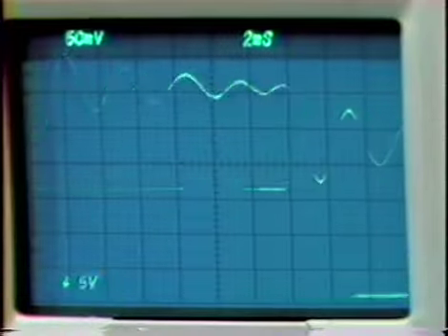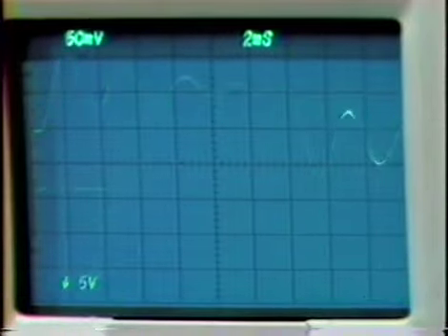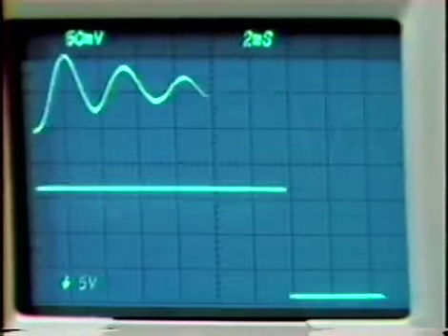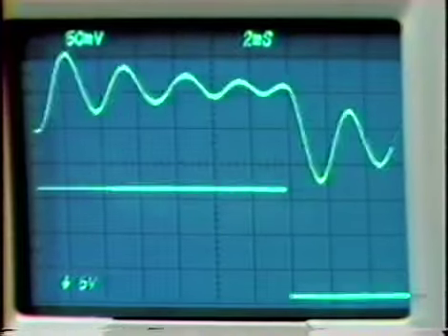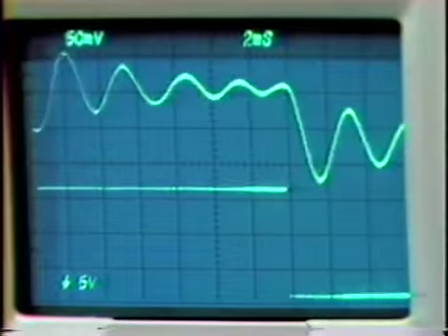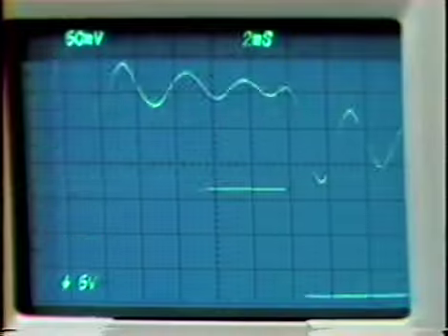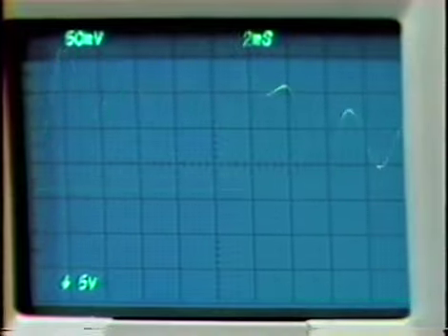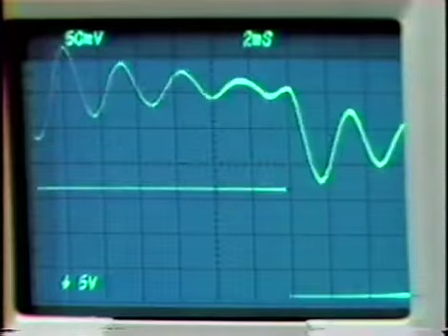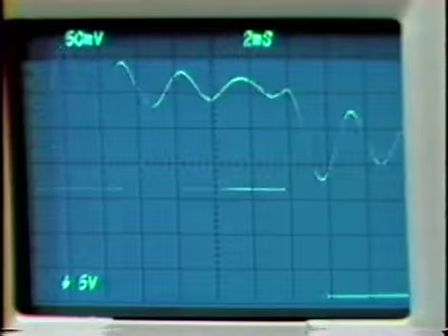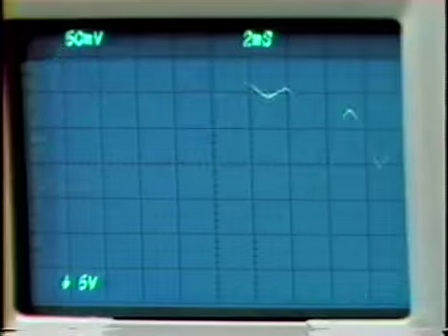We notice on the signal relatively small, we don't really see much ripple at all from the phase detector. This particular system is working at a carrier frequency of about 30 kilohertz, and we cross over at a fraction of a kilohertz, somewhere on the order of 700 hertz. So we're crossing over at a small fraction of the carrier frequency. We're able to do a very good job of filtering the signal out of the phase detector with that sort of spread between crossover frequency and the frequency of operation.